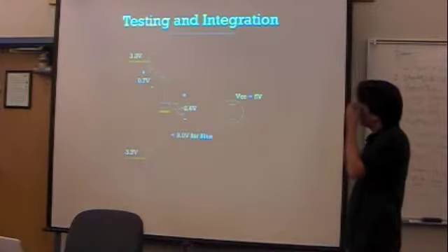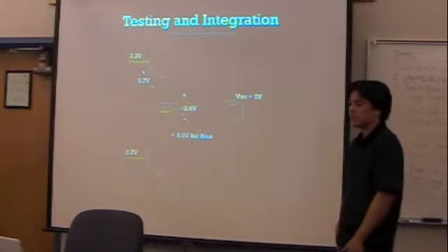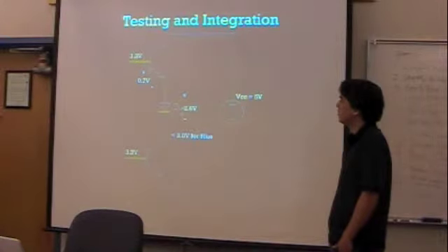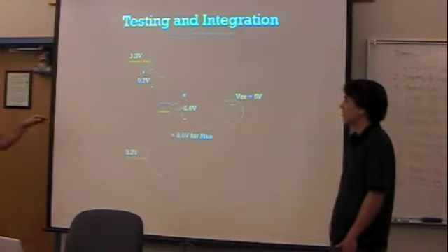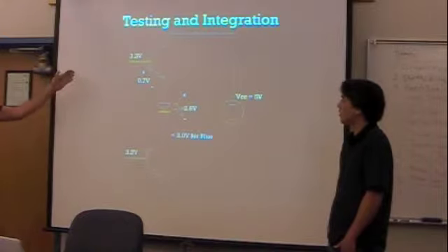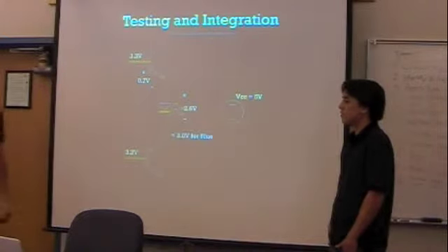And then the testing integration: our original design used BJTs, chosen because as the system grows, you can greatly reduce the number of outputs using the 2 BJT design. But there was an oversight, which is that the blue LEDs require at least 3 volts to light up to maximum intensity, and the silicon drop across the BJT with the 3.3 volts out of the Nexus board will only ever allow you 2.6. So the LEDs were only just barely on.